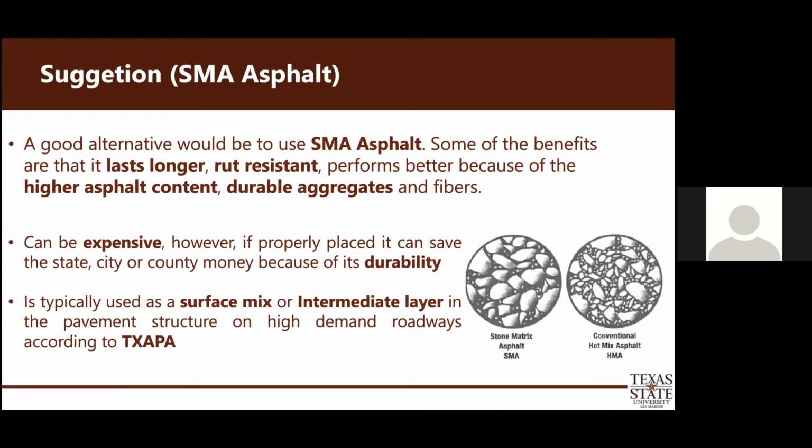Our suggestion is still SMA. It lasts longer and is rust resistant. It has a higher asphalt content percentage. It is more expensive, but it is worth it in the long run. But if it is not properly placed, that will make no difference.